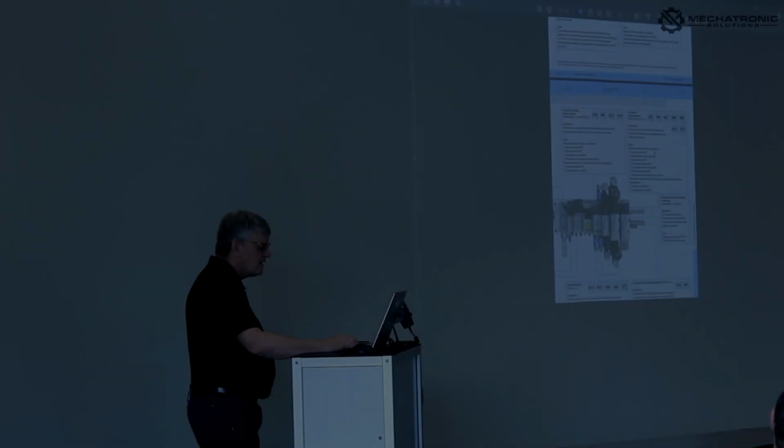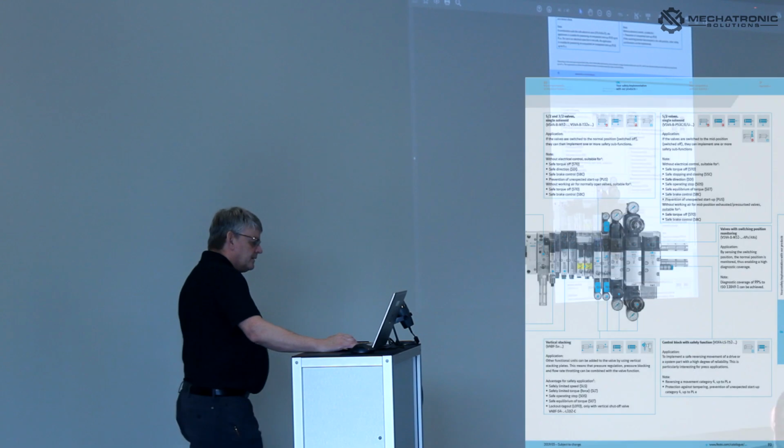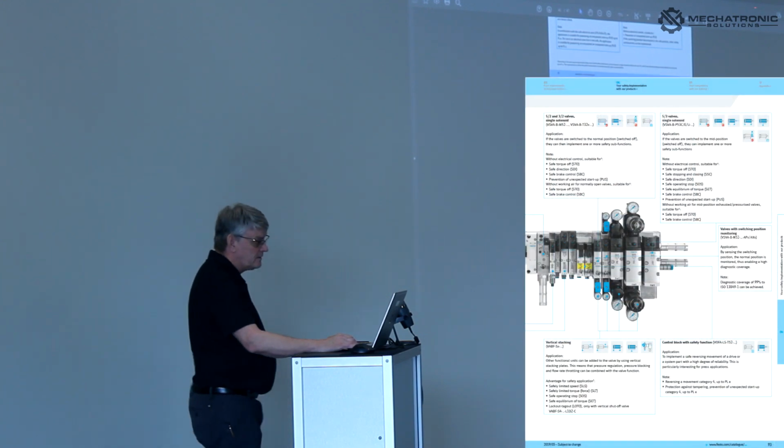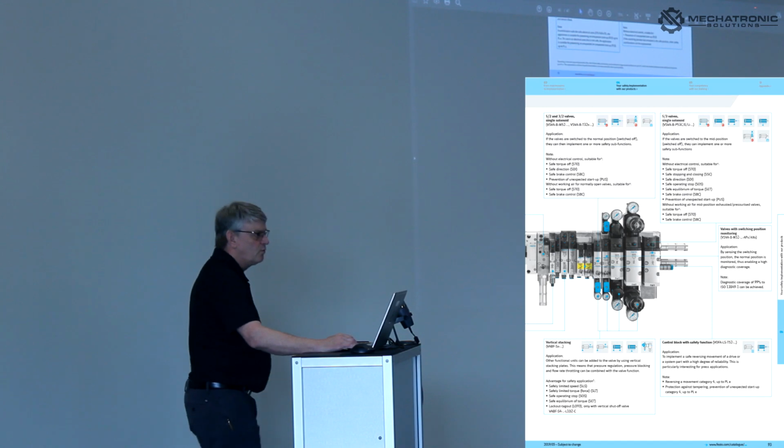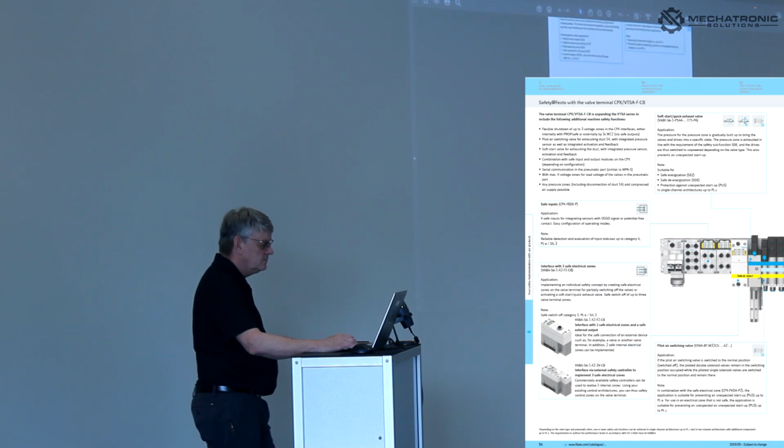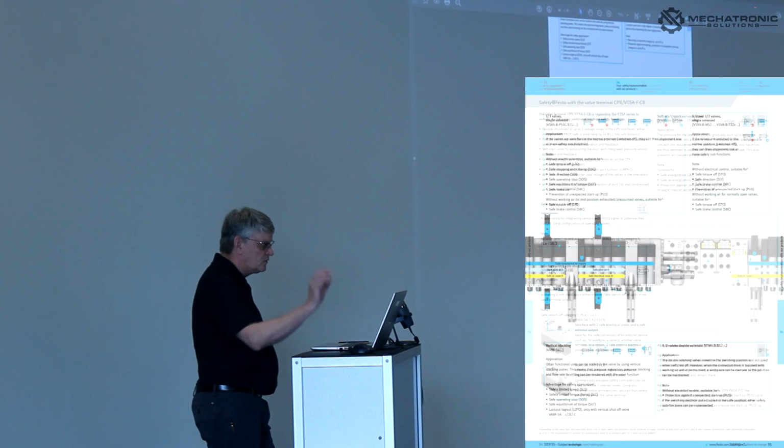We've got some valving. It's safe, it's zoned. We've got it in Profisafe right now. We're working on CIP Safety for Rockwell. We're also working on the EtherCAT side of things. It's on the roadmap. It's going to be a while out yet, another couple of years, I think, a year and a half, two. But the VTSA, if you need safety, we've got safety manifolds, but it's in Profinet, which is Profisafe with Siemens. We've even got inputs and outputs for that. They're so-called true safety.